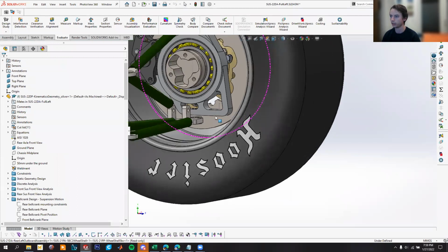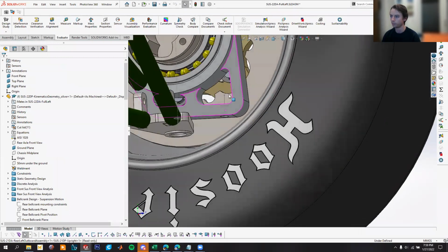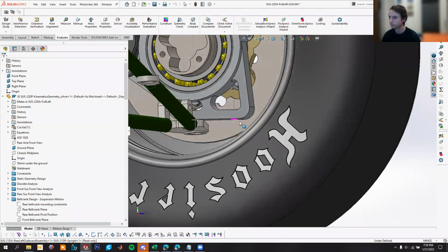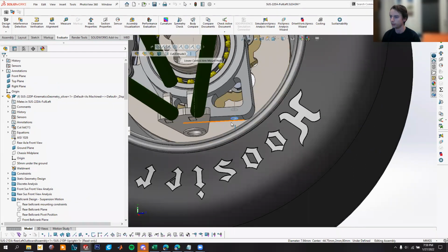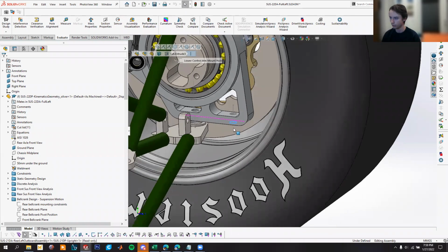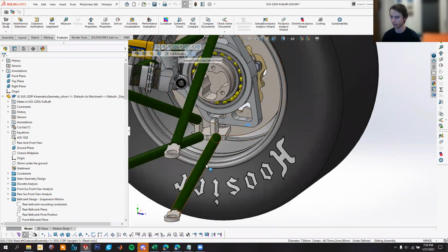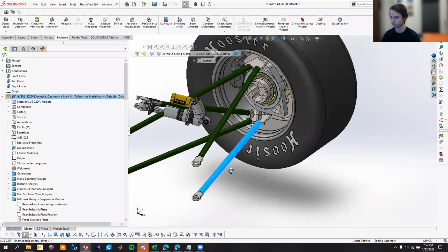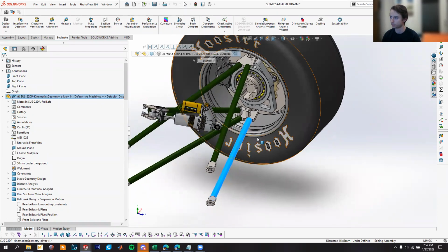So we have to create a link for the rear tires, because they don't undergo steering change. We can use the intended mounting point rather than modify both the front and rear suspension. We can just attach to the original mounting hole location, then have a tube that attaches to our lower control arm at some fixed position.